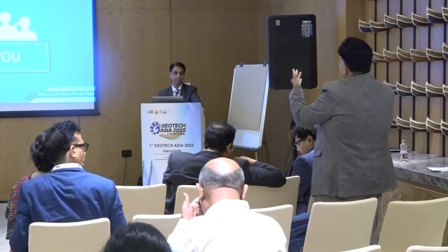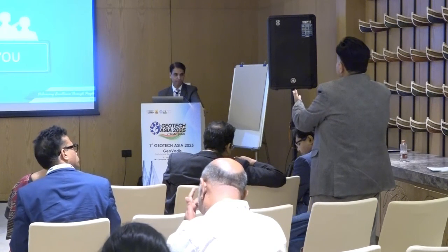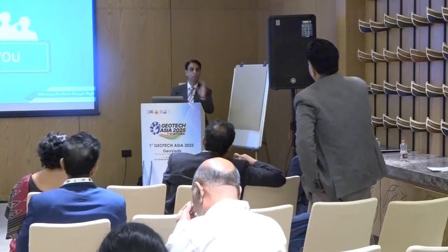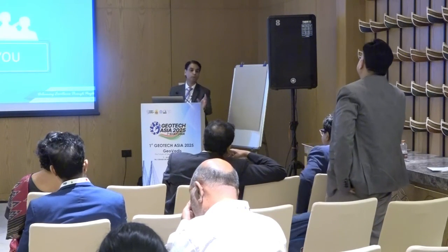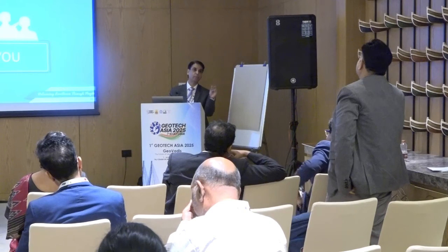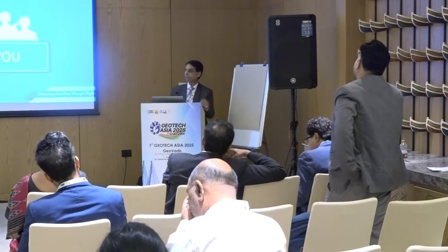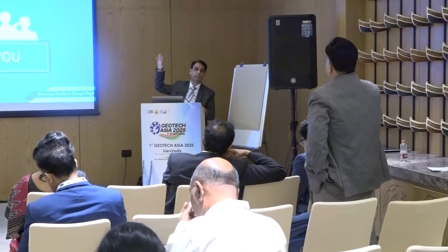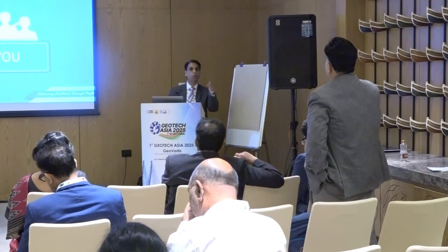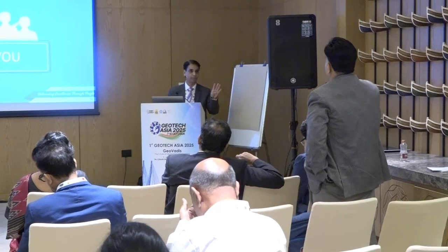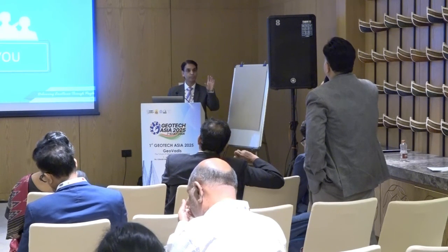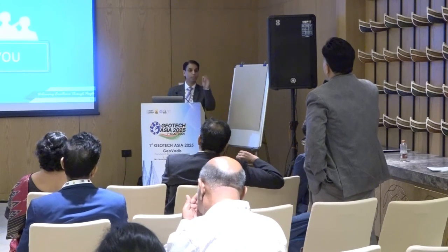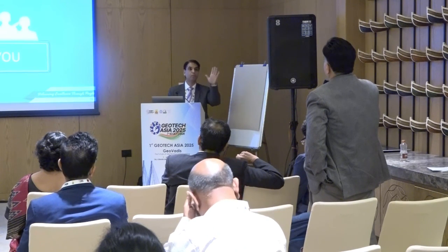So these do have a life of 20 years, 25 years. After that, don't you think it will fall? No. Once we do the analysis, we take into account that the life of the project is determined by the life of the material that you are using. In this case, it's all shotcrete treated. There is no contact with whatever we are storing, either crude or LPG. There is no corrosive activity. I'm not having a question on shotcrete, but the bolts will not live more than 25 years. Nothing of the steel part is visible. Everything is covered with shotcrete.